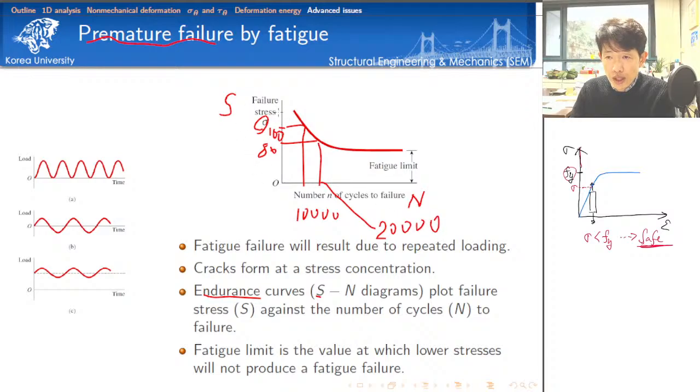So we have to do the test for all these conditions. Then we can obtain the so-called SN diagram, and typically the safety against fatigue is evaluated using the SN diagram. Because this issue is beyond the undergraduate level, we don't want to consider fatigue behavior here, but keep in mind that there is an issue of fatigue.